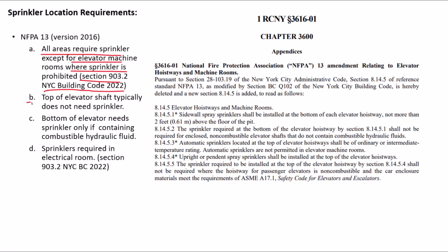Now, go to B. The top of an elevator shaft typically does not need a sprinkler head. If you look at this RCNY, which stands for Rules of the City of New York, they have this section right here towards the bottom. Sprinklers located at the top of the elevator hoistway shall be of ordinary type, and it says automatic sprinklers are not permitted in elevator machine rooms, which I covered in A here.